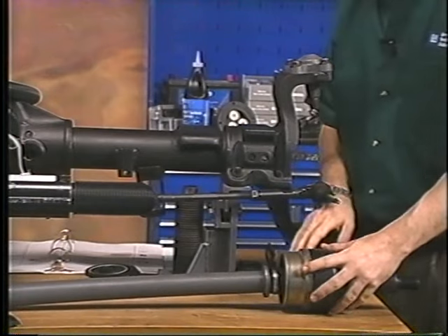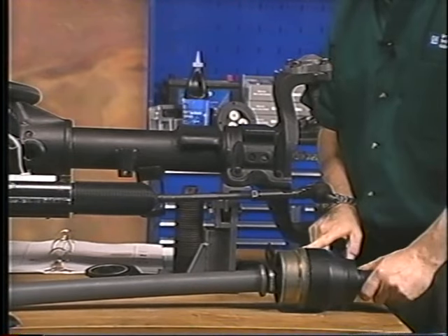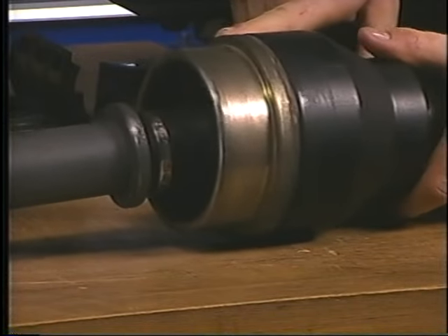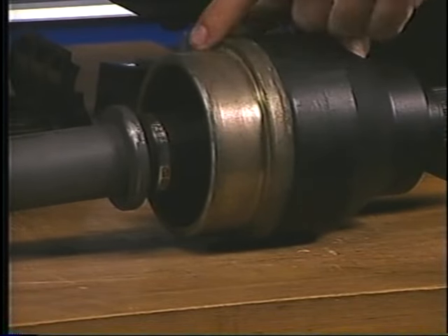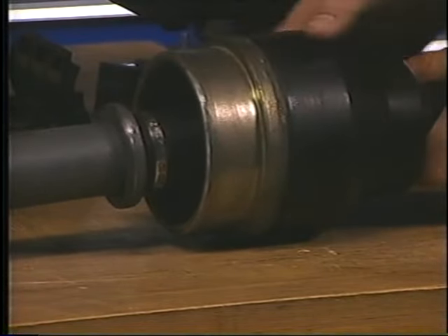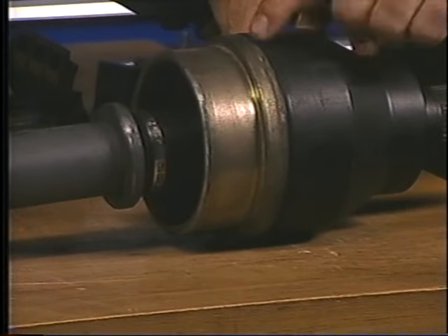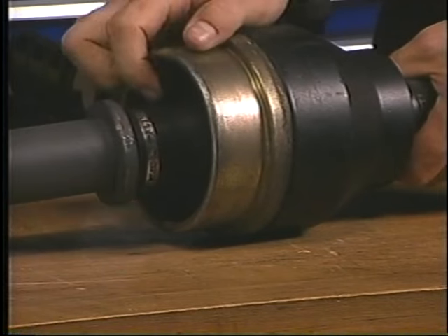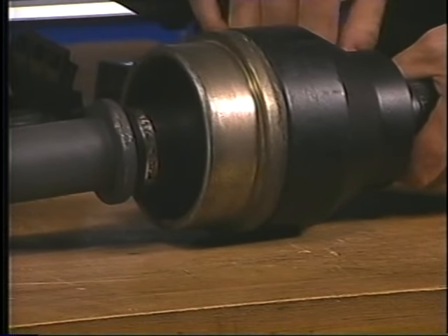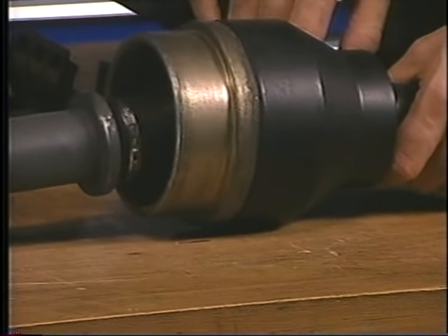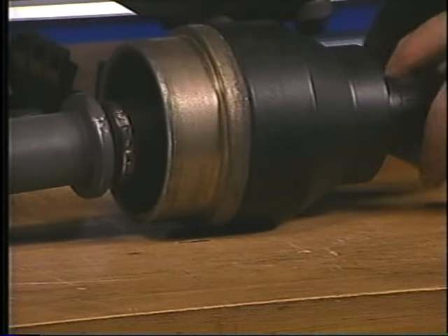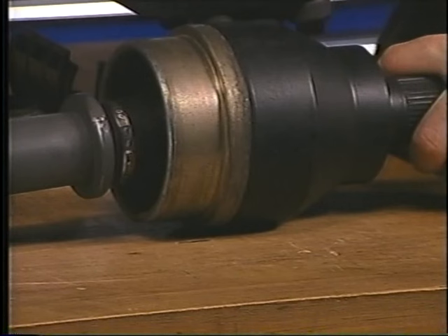And you see, conventional technology here, nothing new. We've got our constant velocity joint. We still have a rubber boot in there, and there you get a good look at it. But look at the way that this thing's manufactured. This gold portion is pressed on, you just simply can't remove it. You may wonder, how do I service that boot right there? How do I replace the boot? Guess what? Don't. If that boot has a rip or a tear in it, you have to replace the whole unit, the whole quarter shaft. It comes with a new CV boot right there.